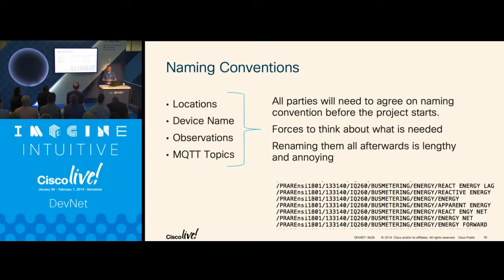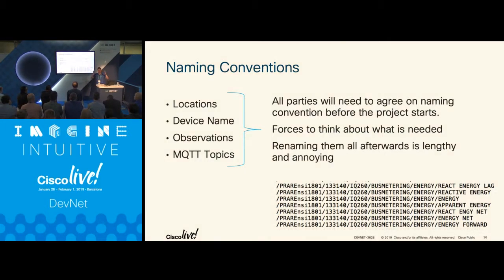And naming conventions, that's a good one. And again, I don't remember how many times we've seen simply location information to be totally inconsistent in the project. So you end up with a complete mess, or you don't know where the machine is, you don't know which machine the sensor is connected to, or they have even 2 different naming conventions. There is nothing you can do with your data if you do not tag your data properly, or if you don't use data model properly. And maybe this is going to be easier early on if you don't do this work early. But it's going to be a lot more complicated later when you will have to do analysis and everything is a mess. So do that early, do that at the edge.